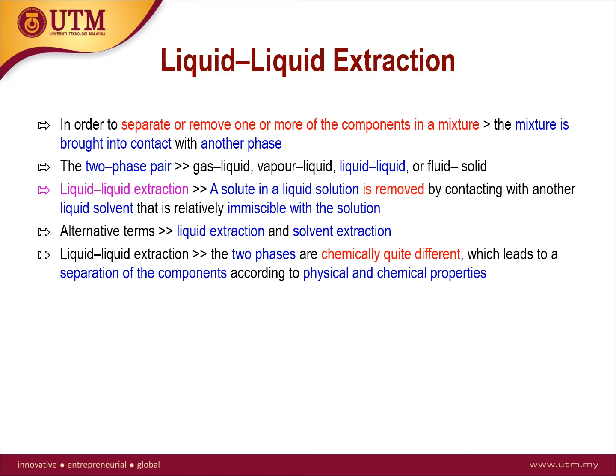For example, once the transfer of the solute from the mixture to the organic solvent, which is the non-polar liquid, is complete, the overall system of the chemical components that makes up the solute and the solvents is in a more stable configuration, which has lower free energy. Then the solvent that is enriched with the solute is called the extract layer, while the feed solution that is depleted in the solute is called the raffinate.